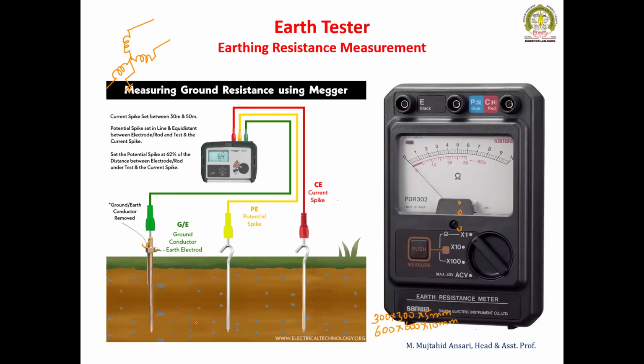The earthing resistance is measured with the help of an earth resistance tester. It is analog type. Nowadays digital meters are also available. For that purpose, two extra rods are buried at different distances, 10 feet apart. And this is the earthing pit under test. This is the earthing pit whose resistance we want to measure, whereas these two are extra electrodes.